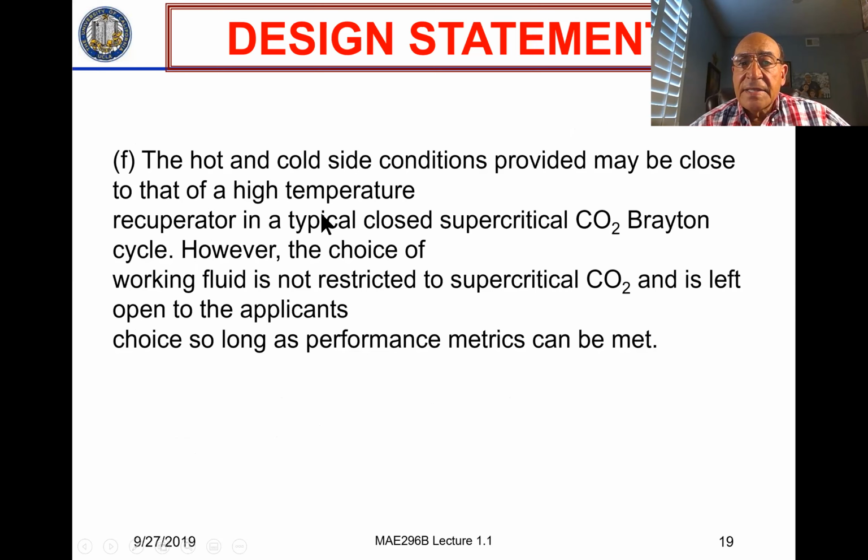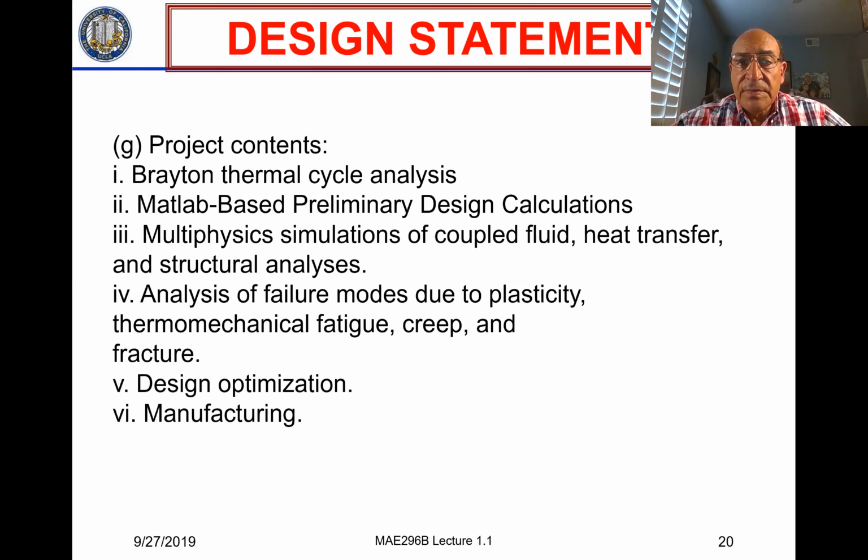The idea is that, as I mentioned, we wanted to focus on what's called a recuperator, and a recuperator is based on a closed supercritical CO2 Brayton cycle. You don't have to use CO2 if you use a different application, but if you want to follow the guidelines, then we can all stick to CO2 as one of the working fluids.